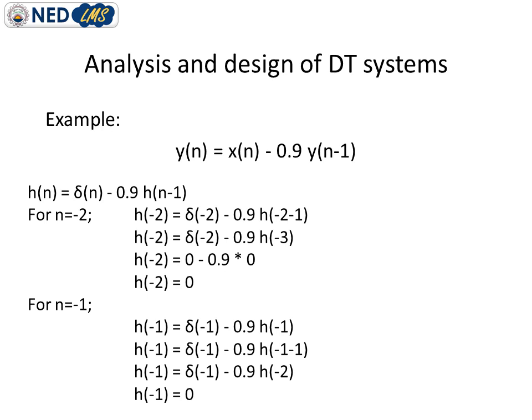Now we are changing from n = -2 to -1 in the next step. When n is replaced by -1, the equation becomes like this, and in the equation you can see that delta of -1, which we know is equal to 0, and the impulse response at n is equal to -2, which is again 0, so the entire impulse response at n is equal to -1 will be 0.